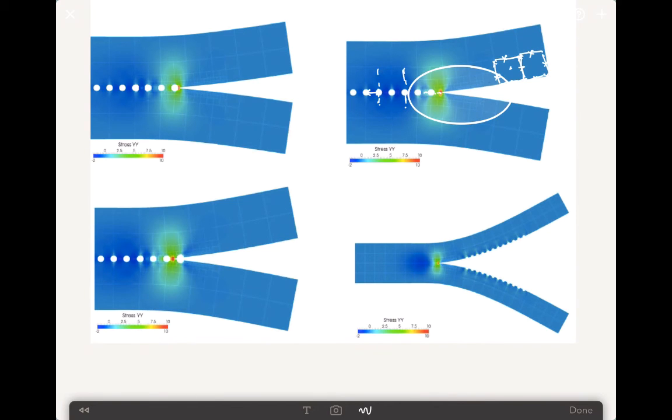If you look at the third one or the fourth one over here at the bottom right, you can see that here the size of the model is smaller. So we started off with a small element length, but at the same time the propagation has happened over a smaller element length, and the results are actually much better in this case than in the case over here. Of course, I can't show you the results here, it's part of a different study, but the idea